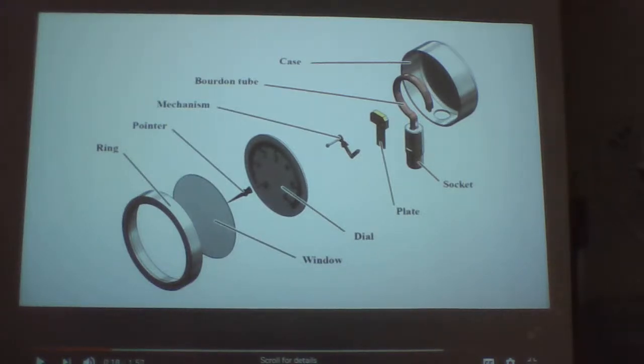And it's often, like I said, made out of brass, bronze, or copper because they are easily movable with pressure. So this tube sits inside of this instrument and it gets air pressure from whatever pressure it's sensing and moves this tool, and that's how it moves the indicator with the rest of these pieces. It's mechanisms that turn the dial and you get your reading.